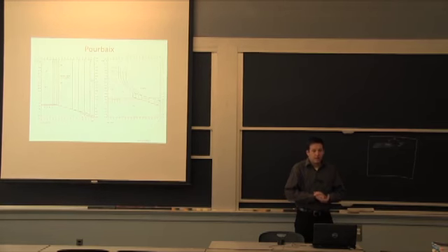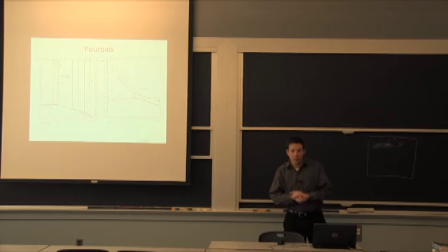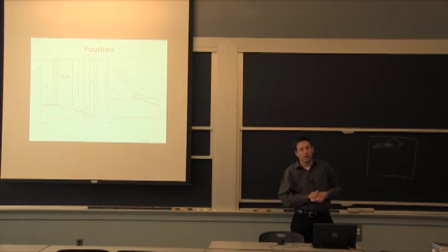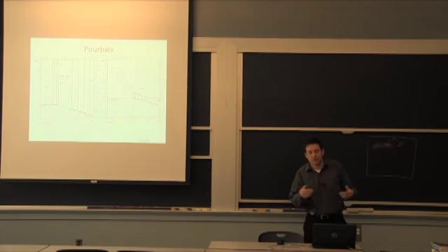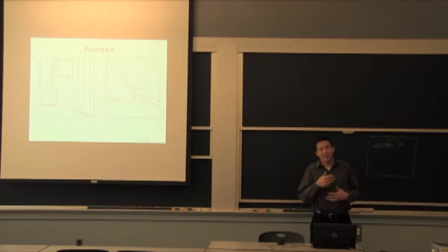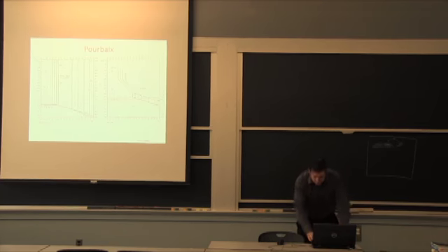So think of aluminum as being good, not so good. It's a very steep variation when you go to a pH below 3 or 4. Below 4 and above 8 or 9 is where the problems are. So you have to think about, is there going to be any situation where I'm going to have some citric acid, or is this going to be cast in concrete for whatever reason, or we use some ammonia solution and we're going to have some leftovers from cleaning. Those are the things that aluminum would be at risk for.